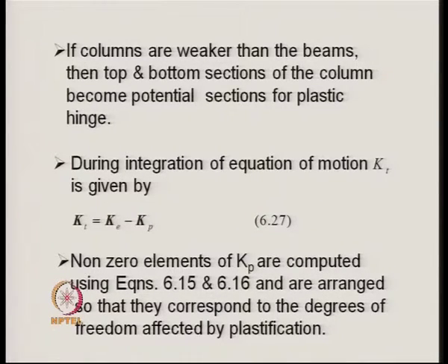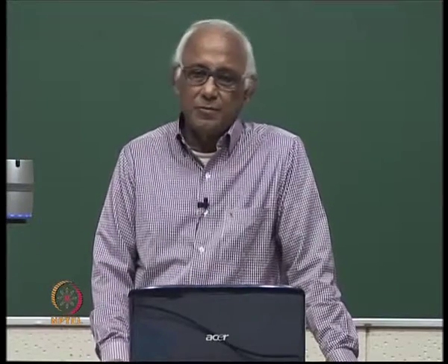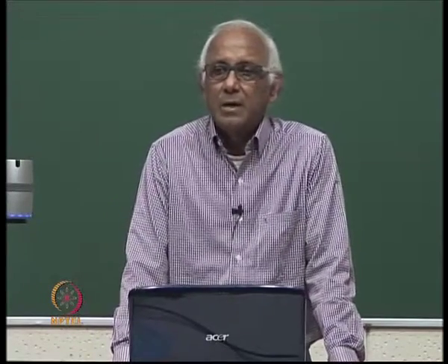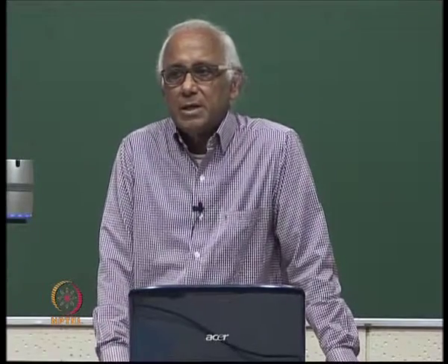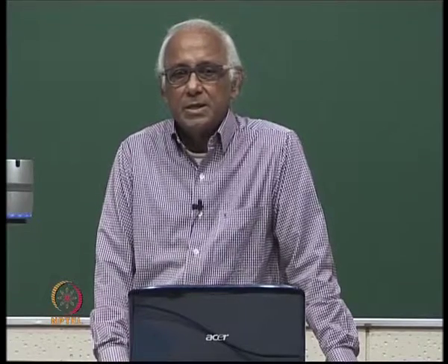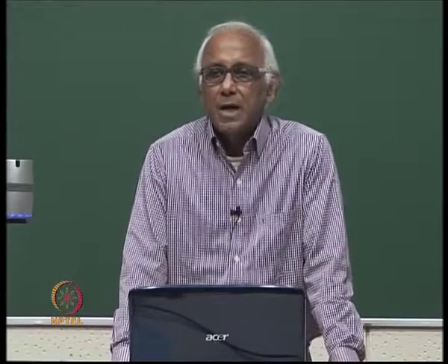By considering the yielding of the columns and the modifications that arise due to this yielding, leading to a modified transient stiffness matrix Kt for the element, we assemble the total stiffness matrix of the 3-dimensional frame. With the help of that modified stiffness matrix, we find the incremental displacement of the system for the increment of loading over time delta t.